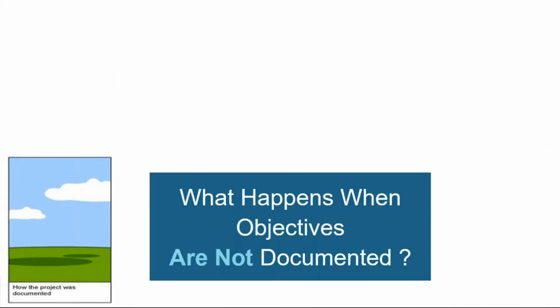So what happens when the objectives are not documented? Any one of those executions would not have been wrong because there was nothing documented. So we like to have, especially dimensional objectives, gap, flush, clearances, all that stuff documented up front as early as possible. Even if it's a placeholder because you don't know what the number is, put it in, get it documented, and then we can report upon it and make sure it is going to be met.